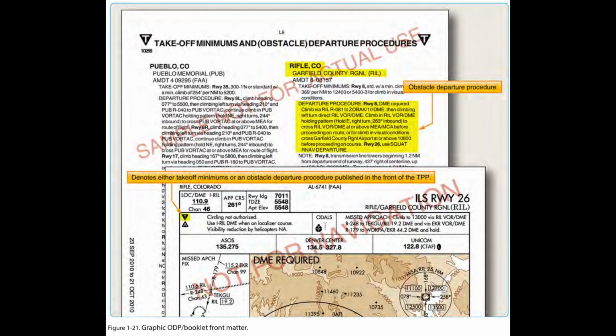An ODP may drastically affect the initial part of the flight plan. Pilots may have to depart at a higher than normal climb rate, or depart in a direction opposite the intended heading and maintain that for a period of time, any of which would require an alteration in the flight plan and initial headings. Considering the forecast weather, departure runways, and existing ODP, plan the flight route, climb performance, and fuel burn accordingly to compensate for the departure procedure.